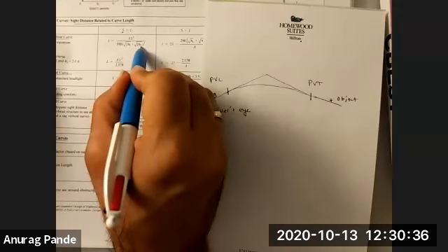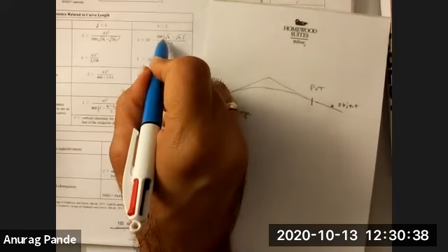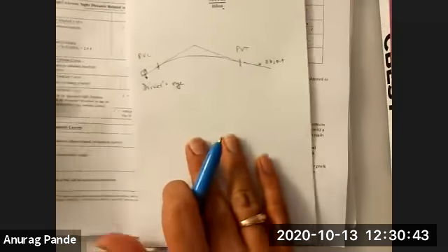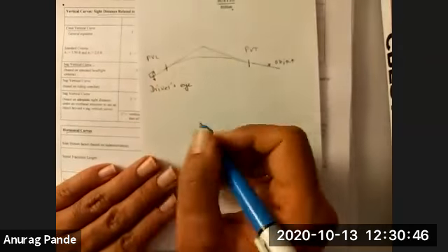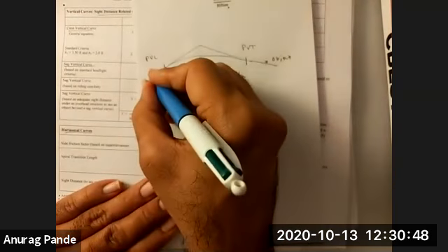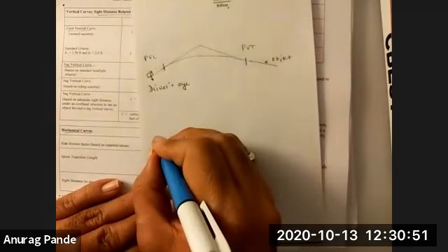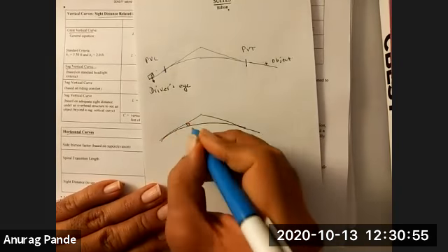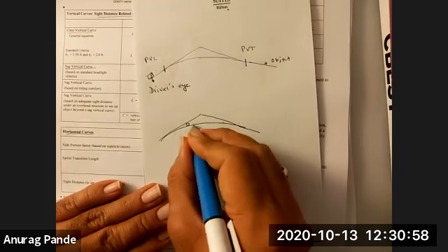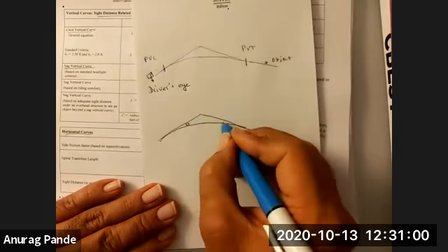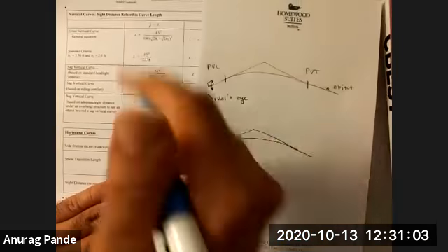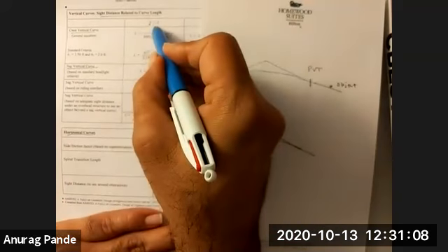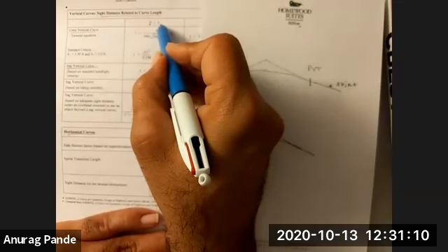If S is greater than L, then H1 and H2 are also defined. These are based on whether the limiting situation arrives when you're outside the curve, or when the driver is already inside the curve and trying to locate the object. When the hill is particularly steep, it may be a short curve that blocks the view, and S is less than or equal to L.